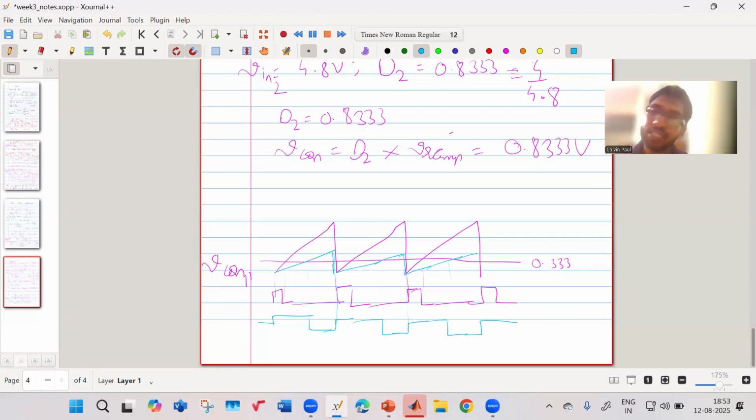And sir also showed, by adding a sine wave, that a sine wave in the input voltage has an effect in the output voltage. Then sir showed that when he added input voltage feed forward, how that rejects it. There'll be a very, very small impact, but it can reject it very well. So that's the power of input voltage feed forward.